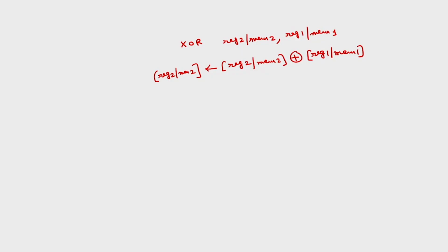So, we can shift the contents of any register or any memory towards right or towards left by any number of positions. First, we will start with a simple 1 bit rotate, RCR. Rotate the contents of any register or memory through right along with the carry.